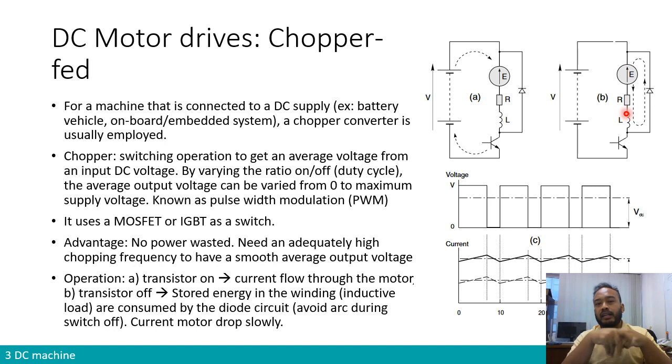There is a peak of voltage that will suddenly be created, and we observe a certain arc, and that is not good for electronic components. So what we need to do is consume the energy that has been stored in the inductance of the armature. So what we do is put what I mentioned just now as a flyback or freewheel diode.